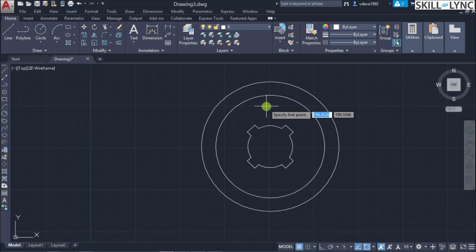The start point let us specify here, and then let us give an arbitrary line, say 100 mm, but the next point as an angular setting is always measured from 0 from this point. So the line should be 15 degrees from 90 degrees, which means the angle is 75 degrees here. So this has constructed this point here.